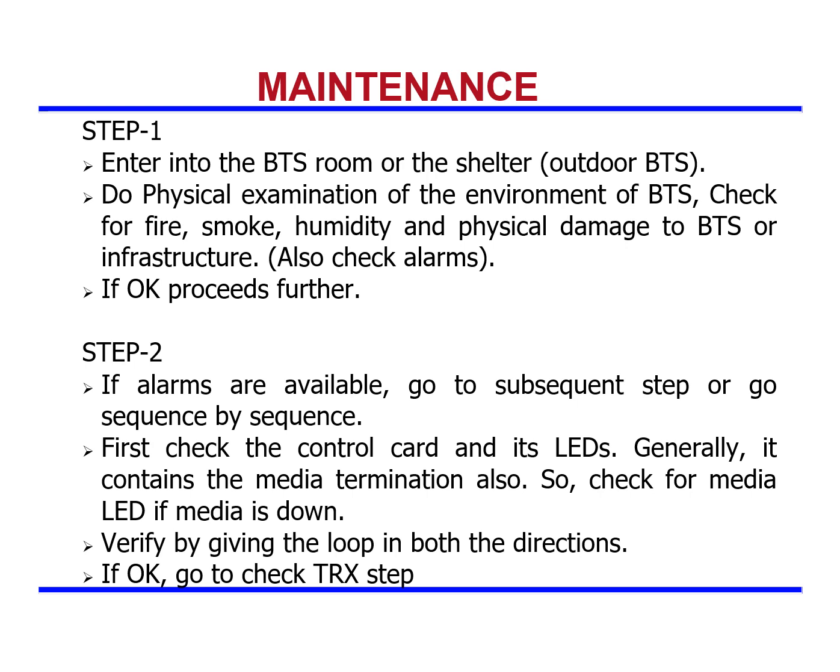First, check the control card and its LEDs. Generally, it contains the media termination also. So, check for the media LED if media is down. Verify by giving the loop in both directions. If okay, go to the next step.